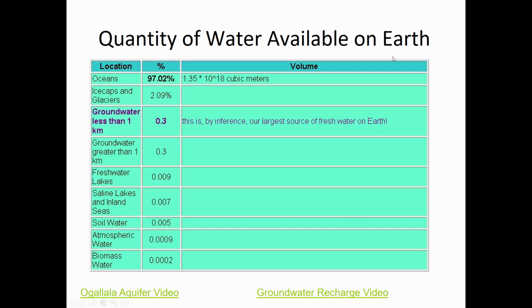So it's just kind of an illustration of a really simple thing that can be done to try and improve the infiltration capacity so that they can extract more from underground if they're improving the amount of recharge. Now, the one thing you have to be careful about is if that same aquifer is used for drinking, then you're allowing surface runoff to go down into the aquifer, and so its water quality could be compromised. Like if there's animal waste in that field, now the bacteria from that animal waste is in the aquifer.